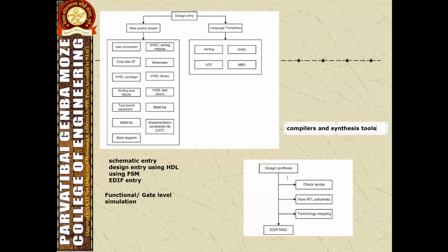The file containing the information about the pins, their directions, and the locations of the pins of the selected hardware device is called the user constraints file. Before implementing the design on the actual device, this file is required to select the particular functional block and configurable logic block on which the design is to be loaded.